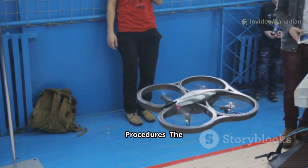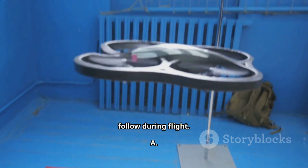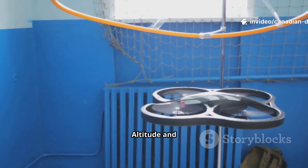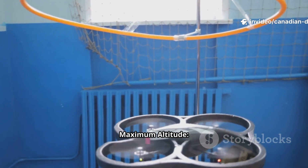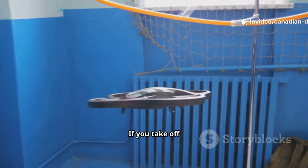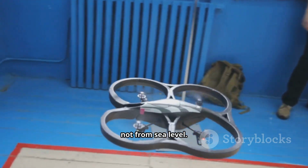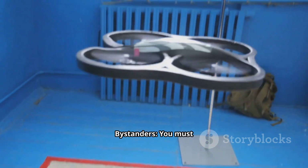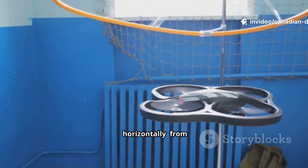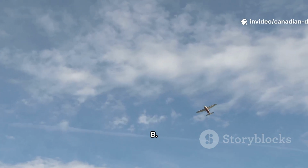4. Flight rules and procedures, the do's and don'ts. These are the non-negotiable rules you must follow during flight. A. Altitude and distance limits. Maximum altitude: 400 feet above ground level, AGL. If you take off from a hill, your limit is 400 feet above that hill, not from sea level. Distance from bystanders: you must not fly closer than 30 meters horizontally from any bystander, any person not involved in the operation.